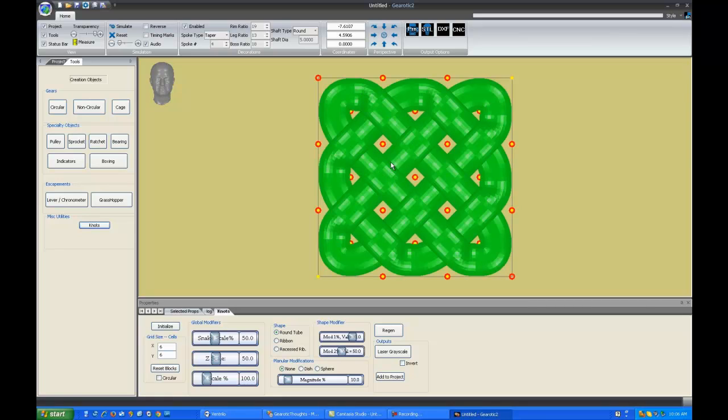All of these red dots are clickable, and if we click on one you can see several others light up white. This is to tell you they are appropriate to draw a blocking line to. So let's draw a blocking line across between these 3 points. And if I release, you can see what happened here is we drew a straight line across called a blocker. And now the thread has automatically repositioned itself to follow the rules.